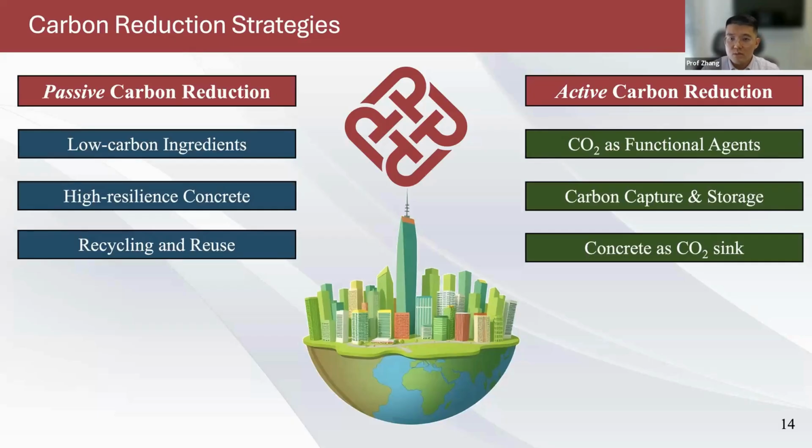And at PolyU, we are focusing on the other category, what we call active carbon reduction. This well-acknowledged greenhouse gas, CO2, will work as a functional agent in concrete. We will integrate CO2, the greenhouse gas, into the concrete production process. During this process, the carbon will be permanently captured and stored in concrete, and concrete will serve as a CO2 sink. Imagine the whole city, a mega city like Hong Kong, becoming a mega CO2 sink. And actually each building has the potential to sequester thousands of tons of CO2 into its material matrix. So this is called active carbon reduction.